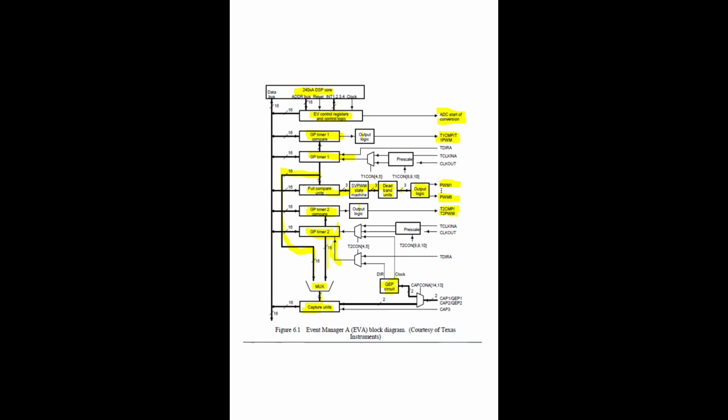So after 15 seconds, you want to operate the analog to digital converter. Let us say you load 30. The 30 is decremented to 29, 28 like that. Once it reaches 15, automatically the signal for the analog to digital converter is given, so that the analog to digital converter will start converting the analog signal into a digital signal.